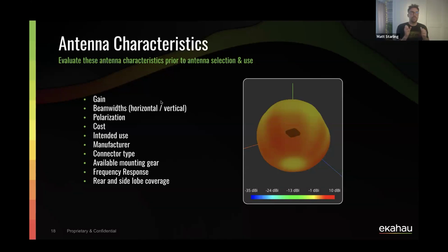It's crazy. Some of the access points now that are available, even with quite directional integrated antennas, they look just like normal omnidirectional access points. So the way that you get the access point physically installed, especially if it's got a directional antenna, can have a big play on how the Wi-Fi is going to perform. If they install it incorrectly, you're going to get a completely different polarization and propagation coming from that access point antenna than you had planned for.